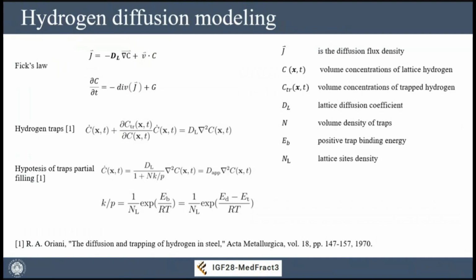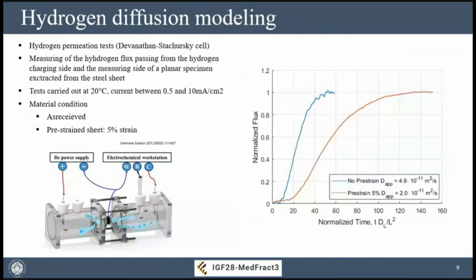of the hydrogen flux that is moving towards the material or within the material, and also for introducing it in more complex models that, apart from just simple diffusion, introduce the effect of hydrogen traps, so material irregularities like grain boundaries, dislocations, and/or defects that can act as hydrogen traps, reversible or irreversible, and can govern how the hydrogen diffuses in the material or how the hydrogen accumulates in some region of the material. We measure the